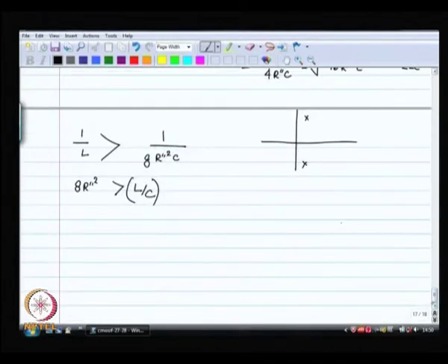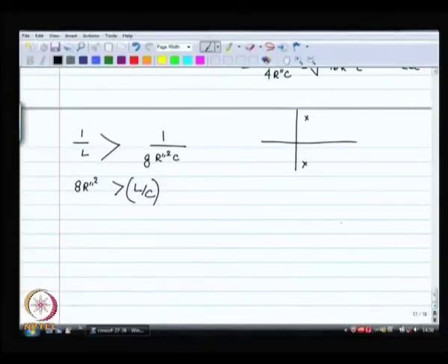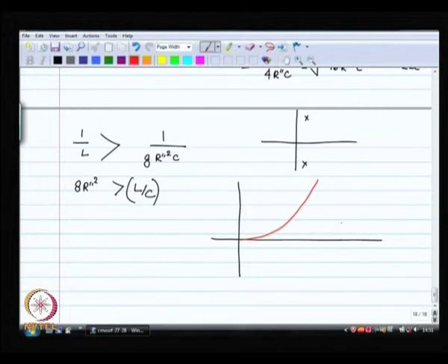Now, what happens when I have two poles which are a complex conjugate pair of poles on the right half plane? What happens when they are on the right half plane, complex conjugate pair of poles on the right half plane? The impulse response of such a thing is, I do not know if you remember, it is a rising exponential modulated by a sine wave.